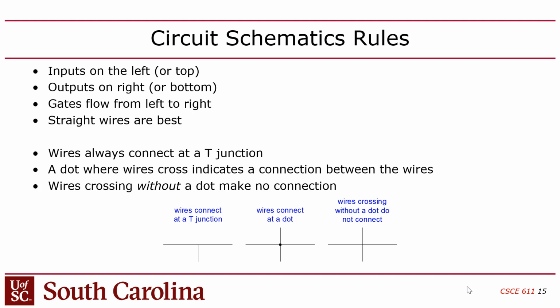The basic digital logic building blocks, like gates, muxes, decoders, and flip-flops, have standard IEEE symbols. But as you go higher and start putting down a register file, or a floating point functional unit, or a control unit, there are no symbols for that. So mostly it's just blocks.